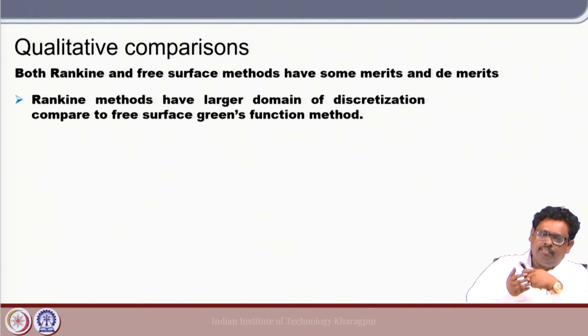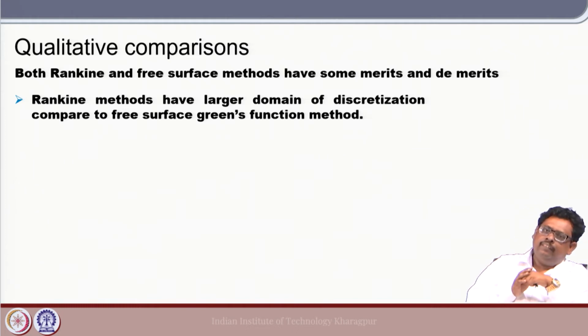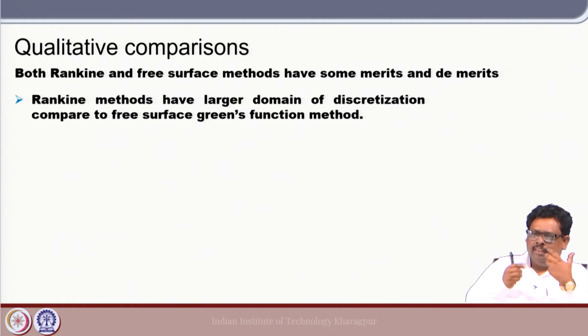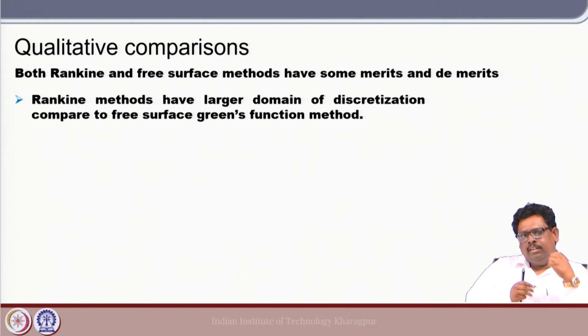When I say CFD, I mean the RANS based solver, which is finite difference or finite volume. All methods have some merit and demerit, but the panel method is very successful and very popular when you deal with seakeeping analysis.